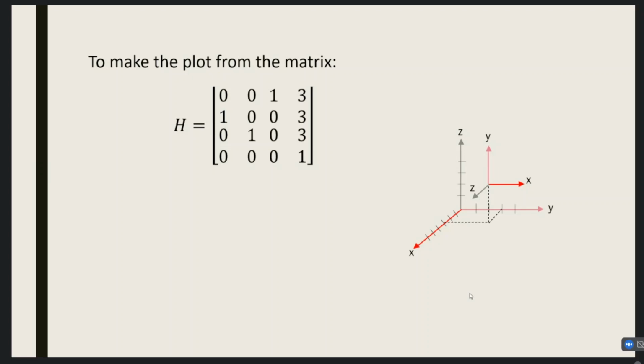To recognize how the plane rotates, we only review the rotation section of the homogeneous matrix. The first column is the direction of the x-axis, the second for the y-axis, and the third for the z-axis. We will do more examples with different rotations in this video.